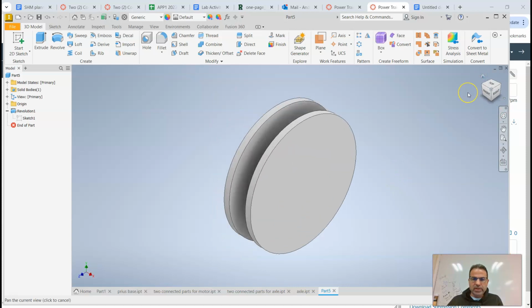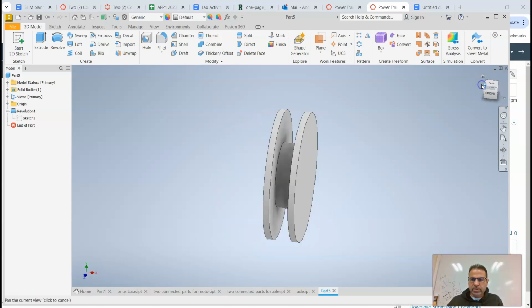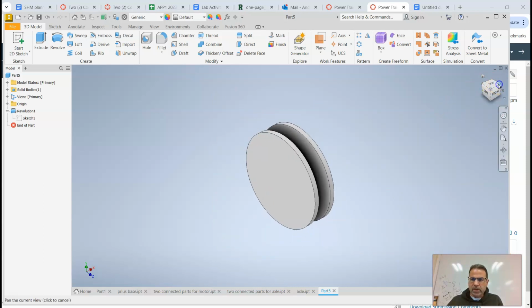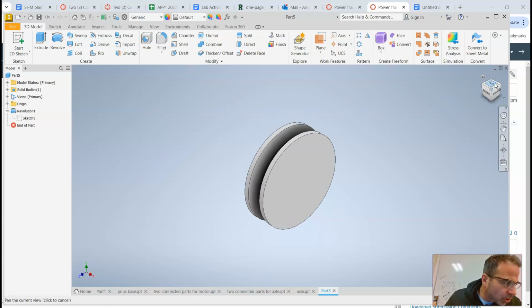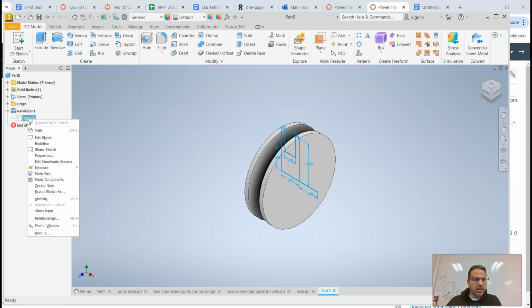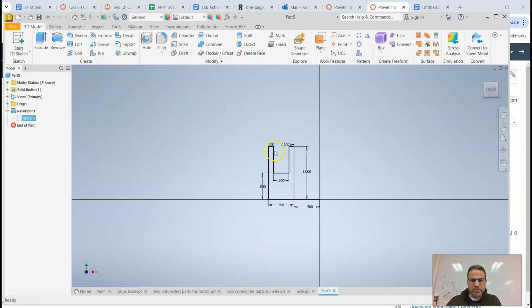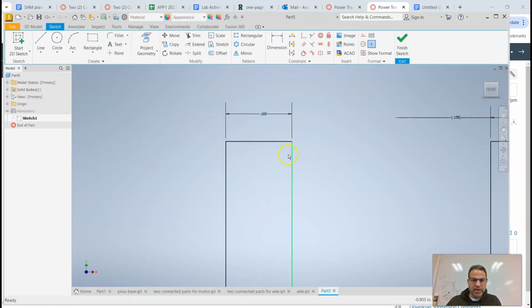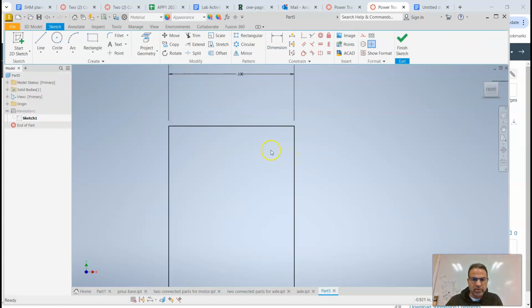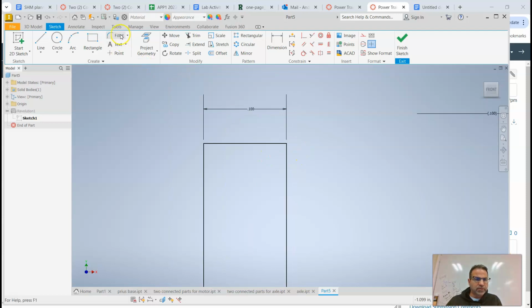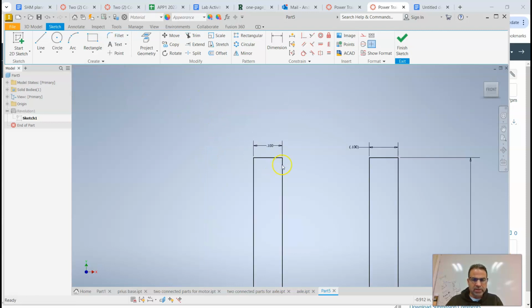So you might need to play with the dimensions a little bit to make it look like a wheel. If you want to achieve some of the curvature or curviness that exists in the sketch, you can get fancy. I'll show you what I'm talking about. If you zoom in on this edge, it's not really a sharp edge. If you want to make it a little rounded, you can use the fillet tool and click on both lines. Whoops, escape. I was clicking on the wrong side.